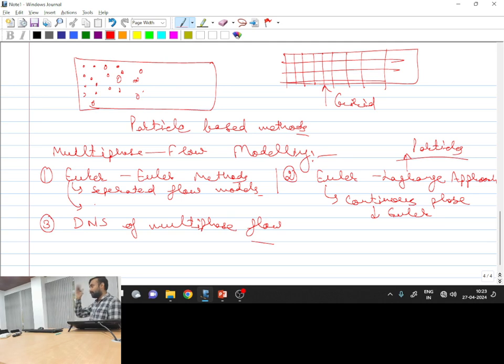If you recall, in one of the lectures I gave you an equation: mass of particle times dV by dt equals drag force, lift force, then some history force and some added mass force. All these forces we have to account for.